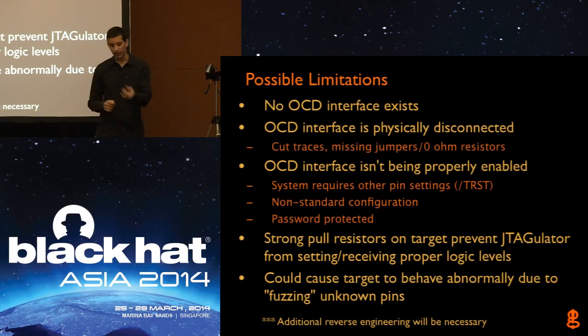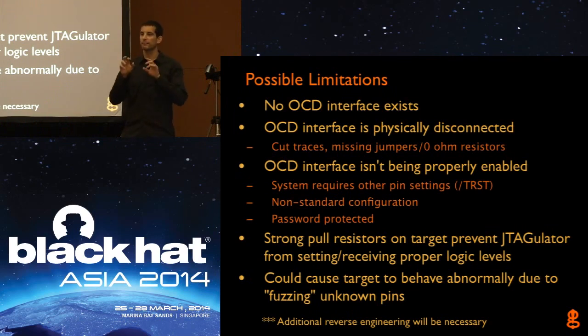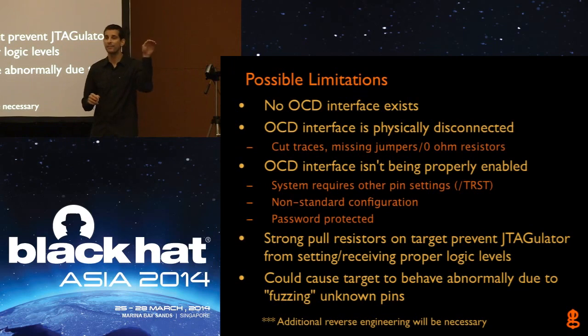What we have right now with the current firmware that's available on GitHub and that's on the units, any pin that we're not currently manipulating, any channel we're not currently manipulating, I have set high. So if there is a reset pin, it's going to keep it high, so it's going to enable it.